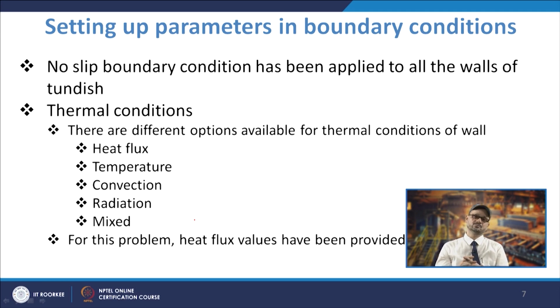Now, when we talk about the wall boundary conditions, many a times we can take the low Reynolds number models also, because in the vicinity of the wall they take the flow to be laminar, and in that case you will have more grids near the wall, and that is why they sometimes take larger time.